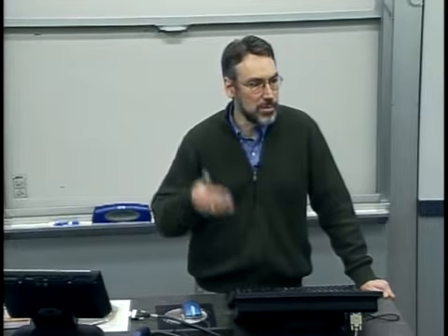And so what I'm going to talk a little bit about after flying through the whole process sequence is some of the types of variation that arise in microfabrication, with emphasis on parametric variation. And then we'll talk a little bit about temporal variation, run-to-run, wafer-to-wafer, if you will, and then spatial variations. Semiconductor processing is an interesting one because there are nestings of replication of the products within additional geometric structures. So we'll talk about that a little bit.